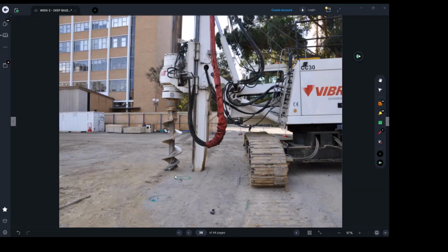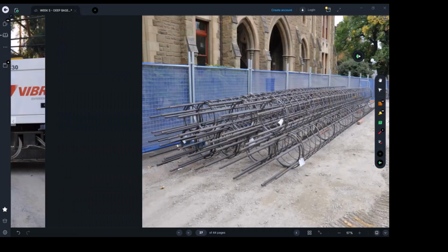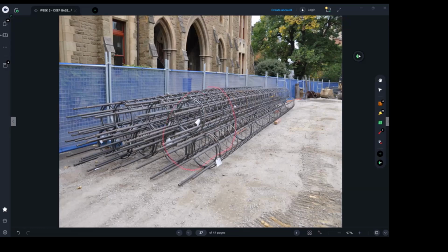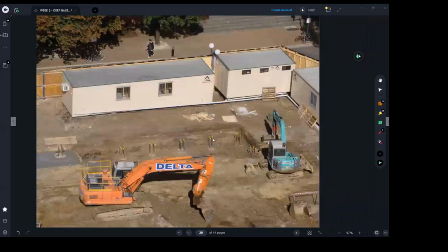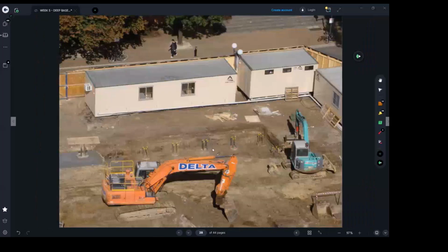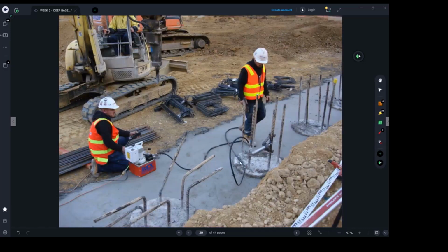They're excavating. Yeah, they're ready. This is the UGO. Yeah, they got a pump, will be connected to it to put concrete. And that's there. These guys are sitting on the side. And the first thing they put is the piles. We have to get some bars sticking out because we need to connect those guys with the level above and the pile cap. Then they're going to pour.